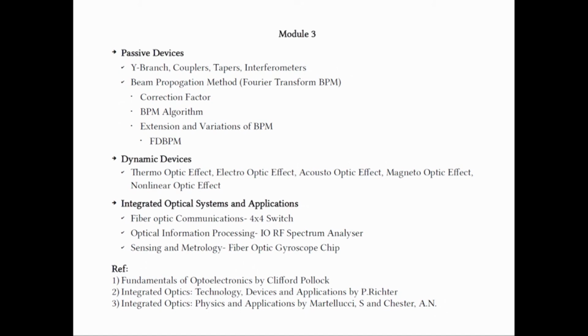So, then we have noted another important application of acousto-optic effect in the form of a spectrum analyzer. A typical spectrum analyzer will consist of an acousto-optic cell or the IDT pattern, which will create a grating on the chip, and we have noted that integrated optical lenses are used for focusing, defocusing, where the functioning can be analogous to that of bulk lenses.